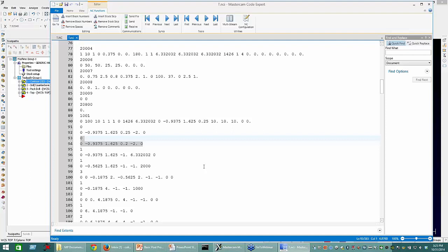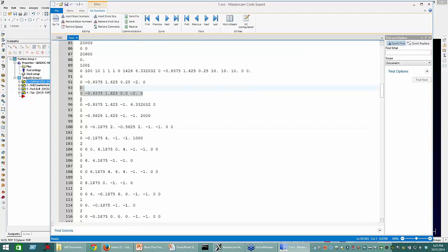So it's this data set that tells the machine to move from point to point or from arc to point or whatever, and this is the data the post processor is configuring for your NC code output. So once we get through here, you'll notice this is a bit of motion. Here's another G1 move. Then we have a G3. So here we're actually swinging an arc, followed by another linear move, a G1 move, another arc.